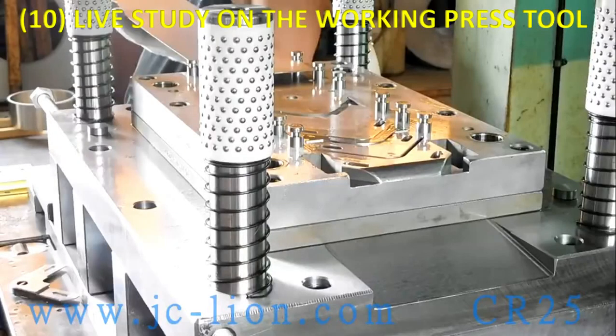Okay, now I'm going to show you a live study about the working of a press tool. Here is a video, and before this, I just want to highlight some of the things. First thing is, it is a 7-stage progressive tool. It is a progressive forming and bending tool. You see various operations, piercing operations going on, and then you see bending operations, then embossing operations, and forming operations in this. And one thing we observe in this tool is that the movement of the strip is clearly visible.